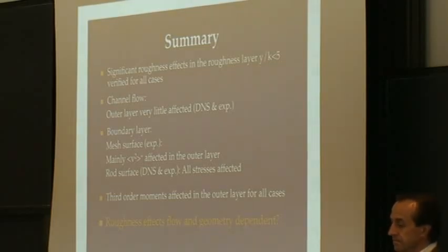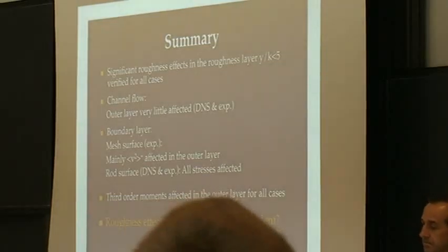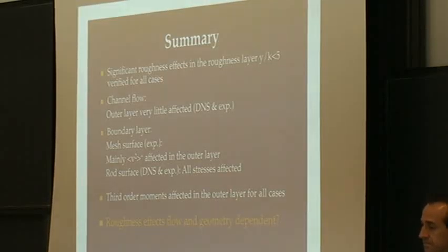If you consider the outer flow structures evolved from near-wall structures, then you would expect the effect of surface roughness in the channel flow would perhaps be much less because the outer structures are non-existent. So qualitatively, it does not look surprising. I don't see any contradiction. No, it just contradicts Townsend's hypothesis, which a lot of people simply believe is correct.